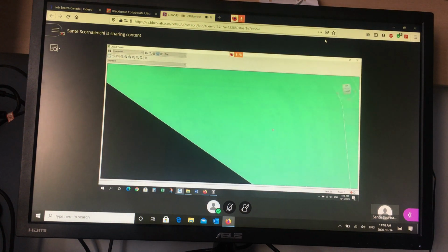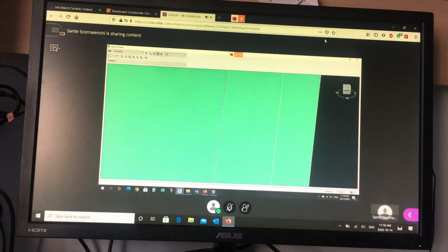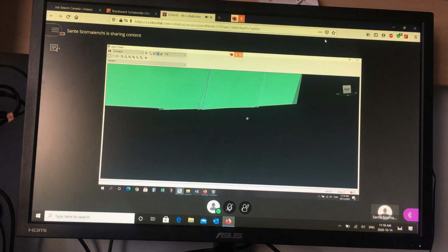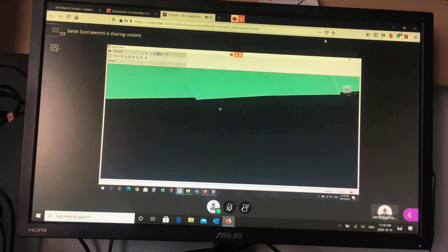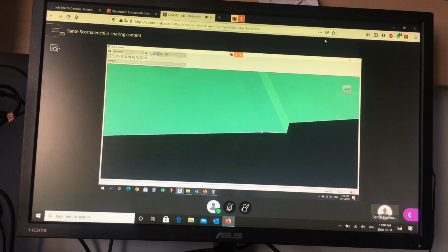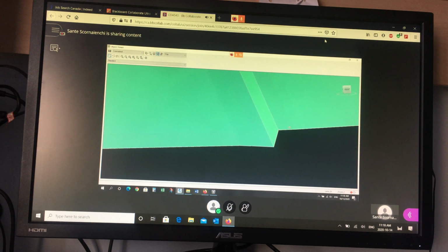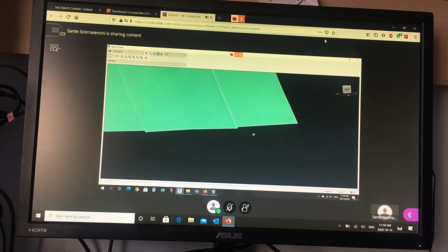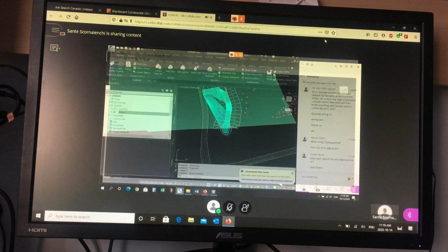So if you look at the road, it might be hard to see. You can actually see the cross section, right? Right at the end especially. Right? You can see, let me zoom in here. You can see here's the center line. Here's the 2% down. If you zoom in here, you can see the gutter. You can see the face of curb. You can see the top flat part, and then you see 2% up to the boulevard. Okay? So it builds a surface.